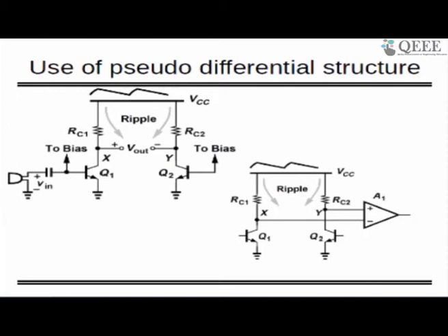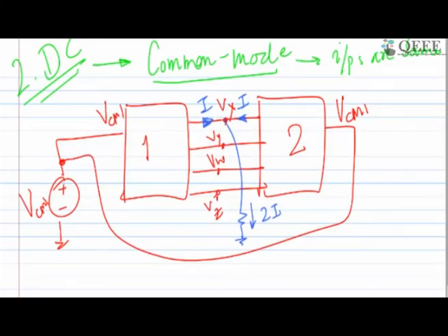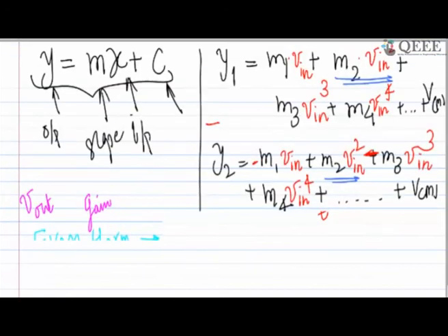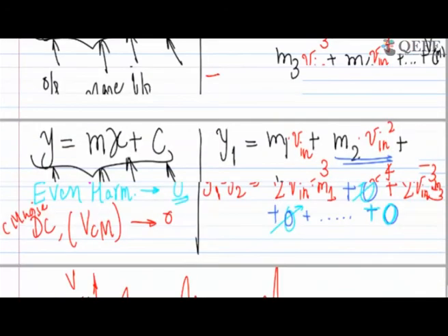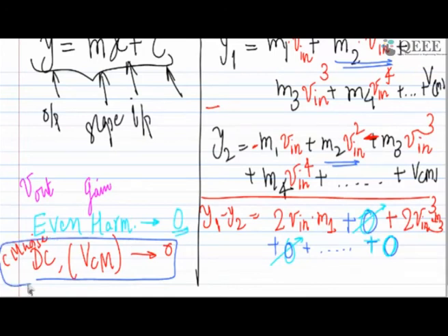But another solution, I told you at the beginning itself, is that differential will be one of the solutions as we are studying the differential amplifier. So what we have to do, you can keep the same circuit at another place. Just look at this part, like V out plus side, you have one circuit, same circuit I am connecting to V out minus side, and if I am subtracting V out plus and V out minus, you can see that the initial voltage or the common mode voltage, as we agreed, your common mode noise or the DC value is going to be removed.